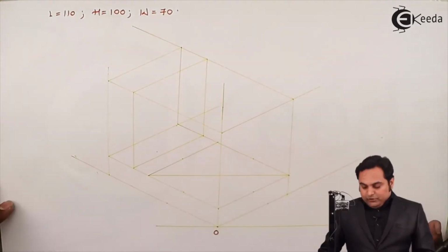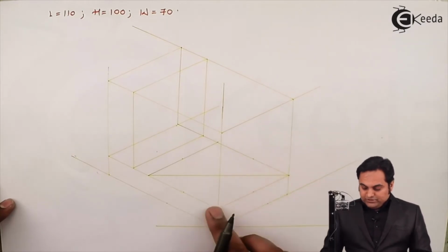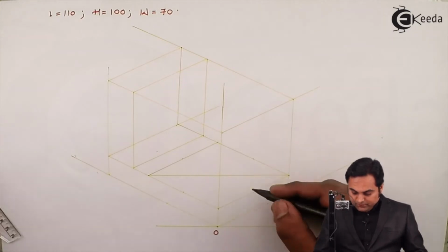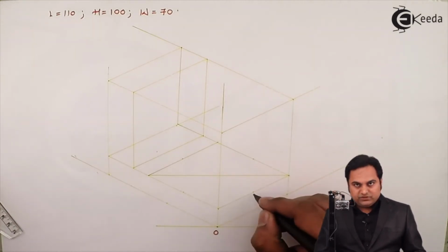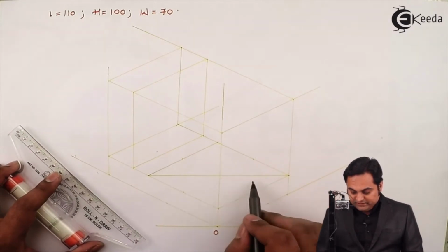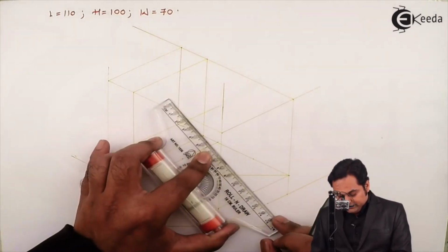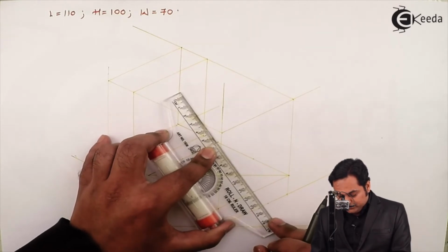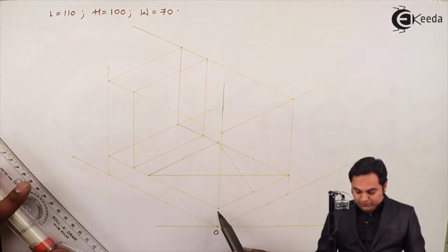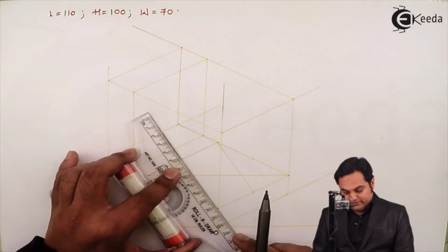Now after getting the midpoint, in order to draw the semicircle here, the next thing would be to join the midpoint here, which is at the top, to the bottom opposite corner in such a way that it will be cutting the longer diagonal. So I'm connecting this midpoint to its opposite corner, cutting the longer diagonal. Similarly, bottom midpoint to its opposite corner, again cutting the longer diagonal.